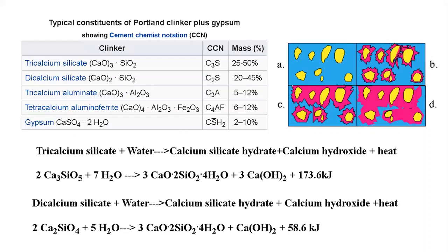And so here's the most nerdy part of the whole presentation, all this chemistry, which I hate, but what you're seeing is the chemical reaction. So the big bulk of cement is these tricalcium and dicalcium silicates that make up 75% or 90% of the cement. You mix that with water and you get the important thing here, this calcium silicate hydrate. That is the core structure that binds the aggregates together and really makes concrete. So this is the most important chemical part of concrete.